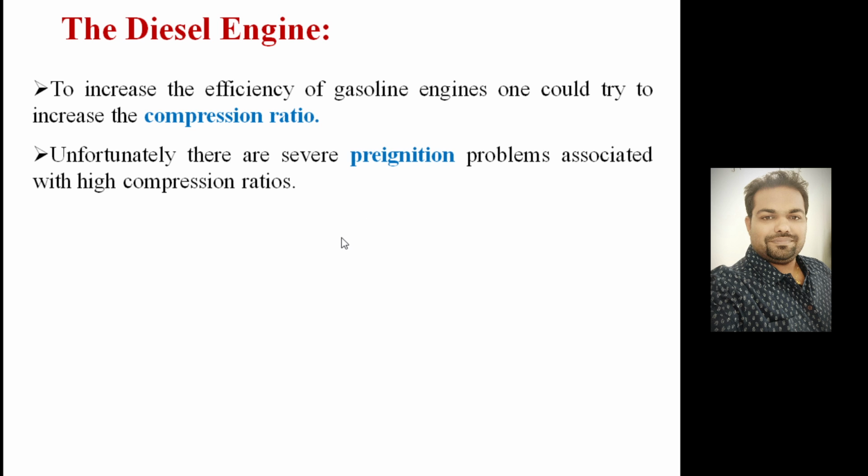In that case, what will happen? First of all, you don't need any spark plug. That is one advantage. Another, the pre-ignition problem will not be there. And if we are using a high compression ratio, efficiency will be high.